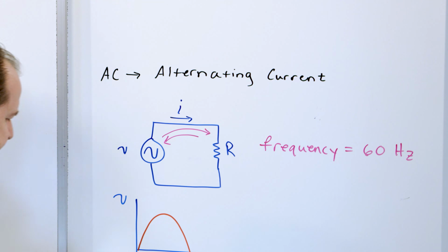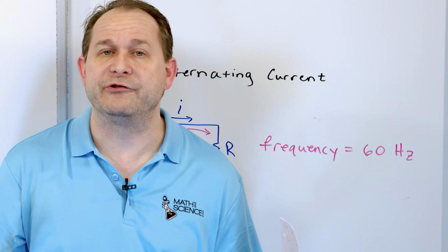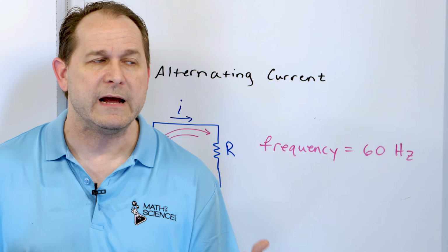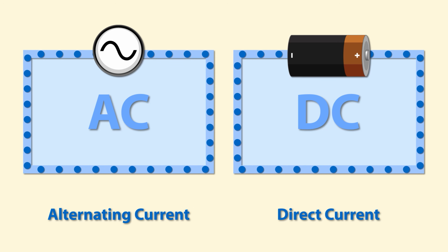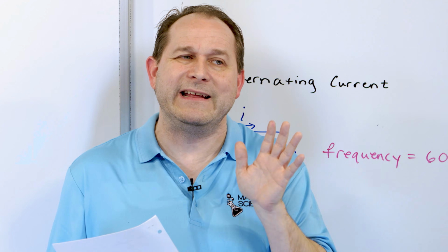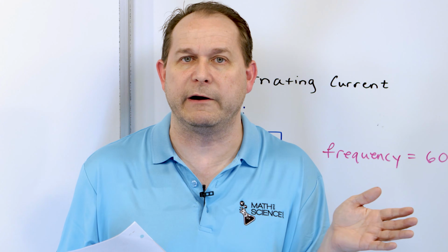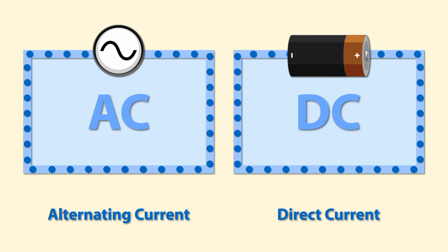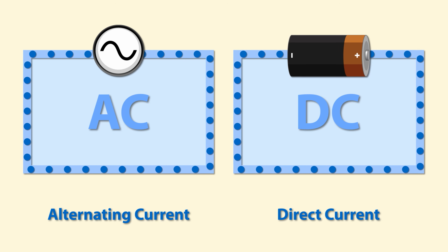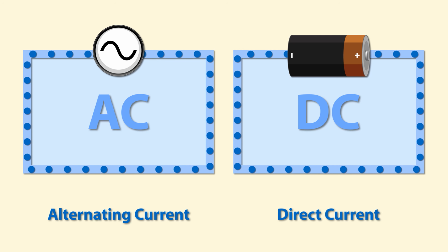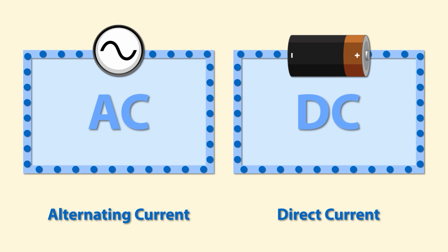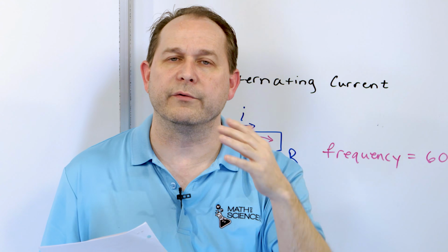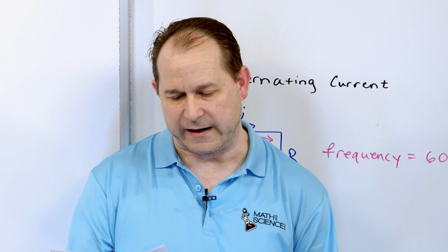All right, that's the difference in a nutshell. So that is the punchline. The difference between direct current and alternating current is that direct current comes from batteries or solar panels. It generates a voltage and in turn a current flow which does not change, and it's fixed over time. It doesn't oscillate or flicker at all, right? That's what comes out of batteries. An alternating current circuit, which is what we use in all of our households and in all of our appliances, has a voltage that oscillates in the United States 60 times per second, but in other countries it's at slightly different frequencies. And in those situations, the voltage goes up and down, and so the resulting current also goes up and down 60 times per second.